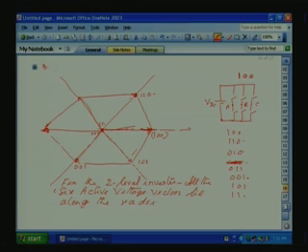Hexagonal radii is this one. For one cycle of operation, if you switch the active vectors, it will be 1, 2, 3, 4, 5, 6. So, the 2-level inverter is also called a 6-step inverter. When the active vectors are switched, it will take 6 steps to make one complete revolution. This is also called a 6-step inverter.